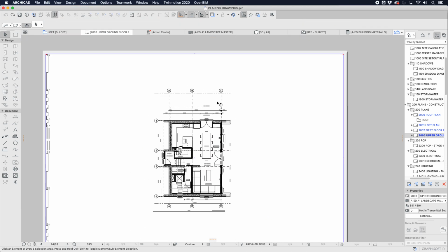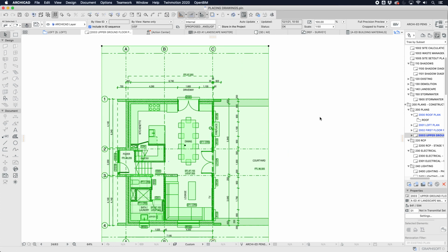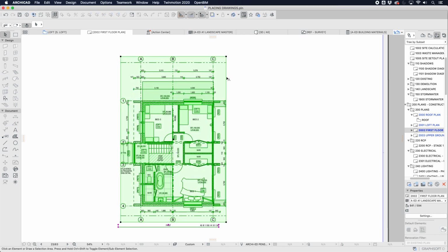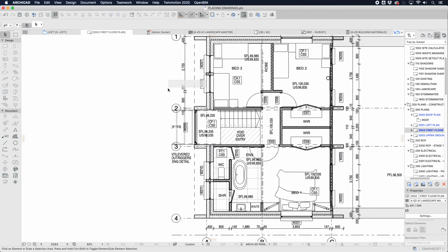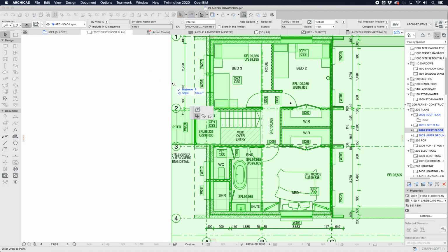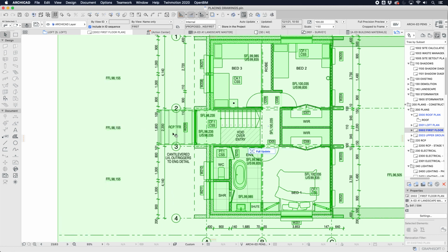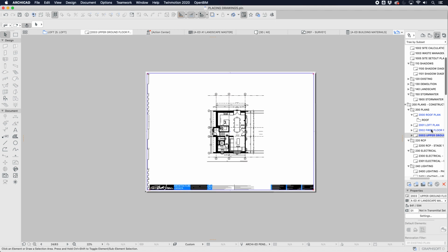what we then need to do is to be diligent to see, am I cutting something off? Yes, I am. Let's click that outside edge and extend it, decide how much we want to keep, and then happy with that result. Let's do that here as well. Click, extend, update frame. We're seeing what we want. We see we've chopped it off a bit on this side. Let's do the same thing. Great. So we've got everything that we want, and now they're perfectly aligned.